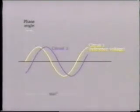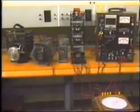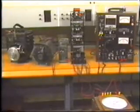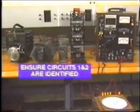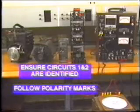There are 360 degrees in one complete cycle, so the circuit is designed to convert the measured time difference into a phase angle reading. When using the instrument, great care must be taken to make sure that the circuits 1 and 2 are clearly identified, also that the polarity marks are followed. Let's look at a simple example.